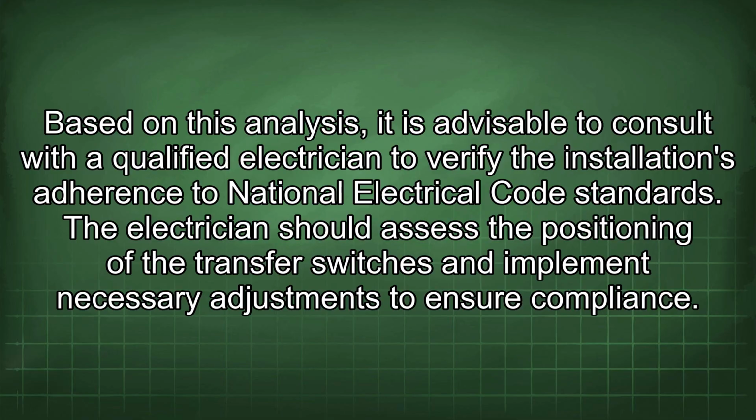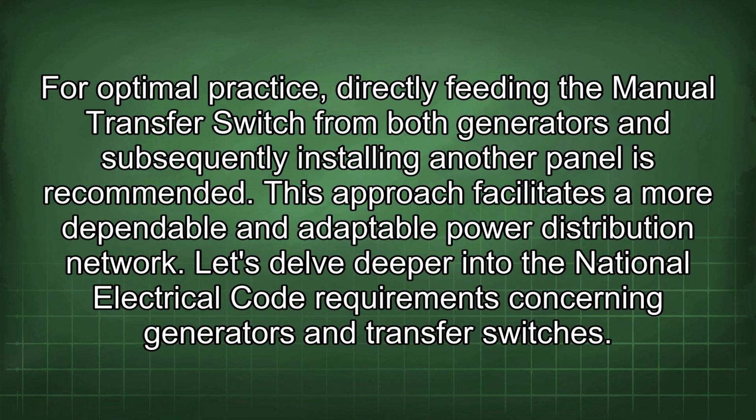Based on this analysis, it is advisable to consult with a qualified electrician to verify the installation's adherence to National Electrical Code standards. The electrician should assess the positioning of the transfer switches and implement necessary adjustments to ensure compliance. For optimal practice, directly feeding the manual transfer switch from both generators and subsequently installing another panel is recommended. This approach facilitates a more dependable and adaptable power distribution network.